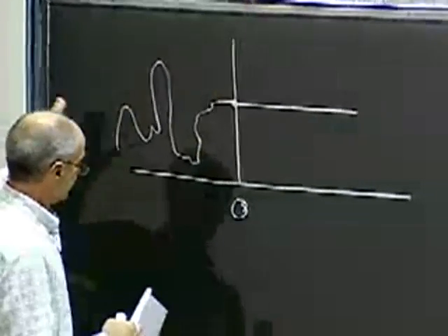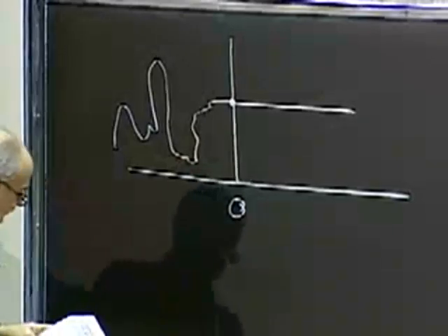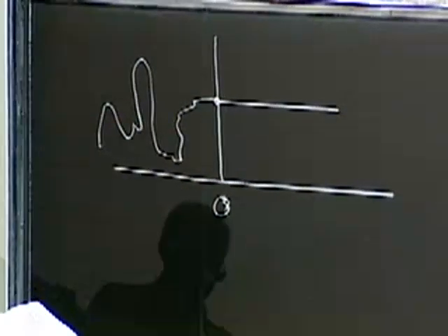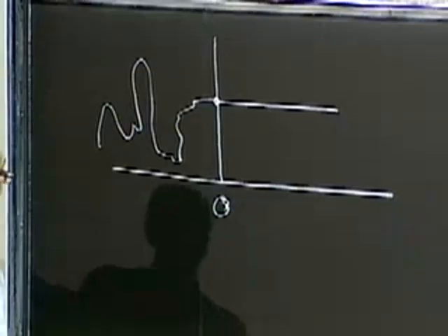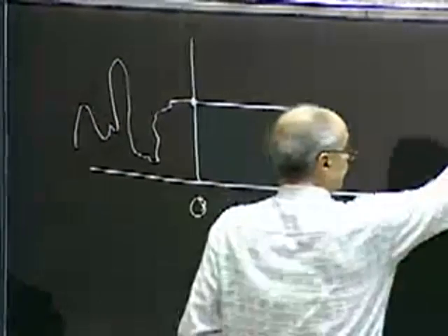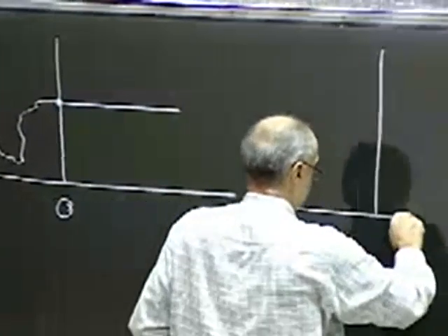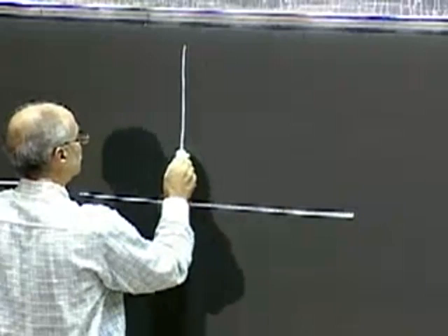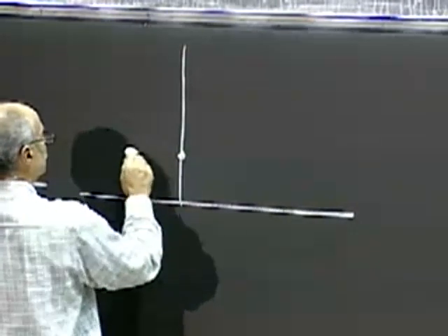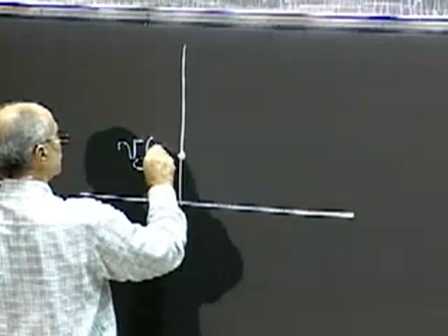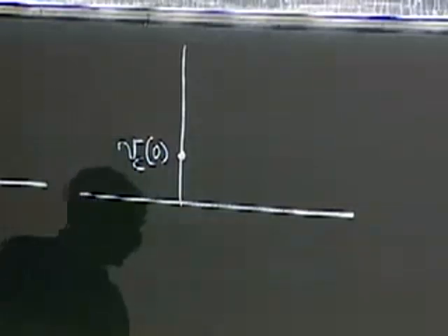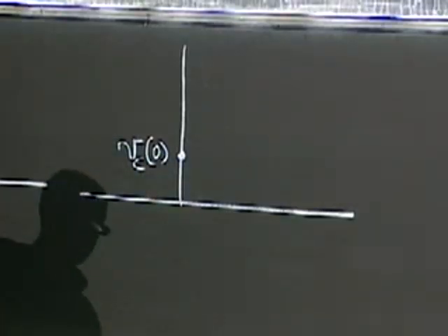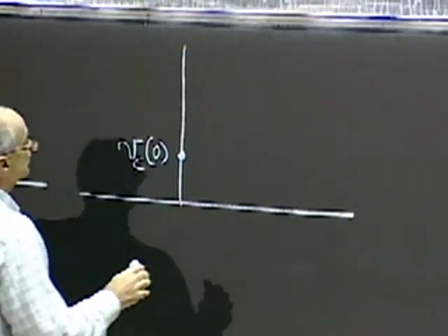And so the history of VI really doesn't matter. The response following that equation that we have there will depend on the initial value, which is Vc of 0 here, the voltage on the capacitor at that time.